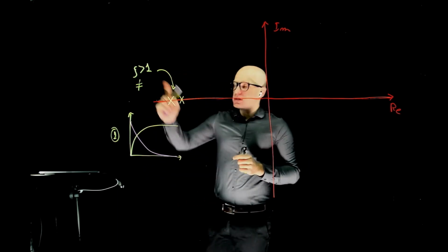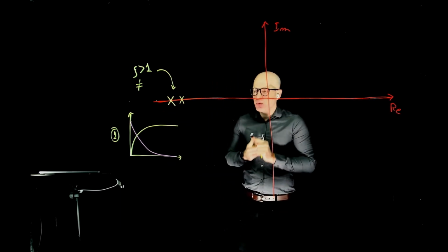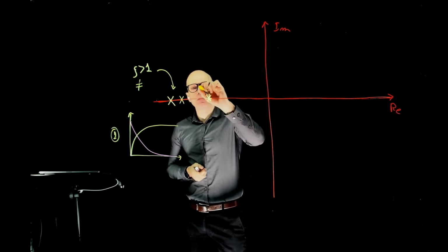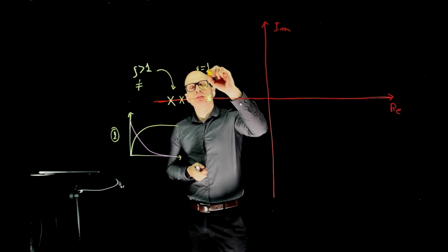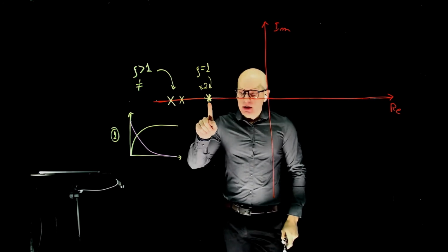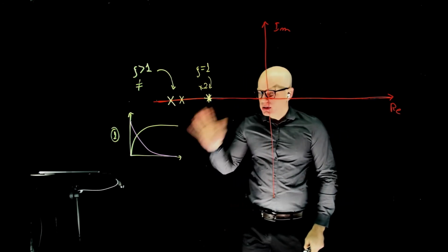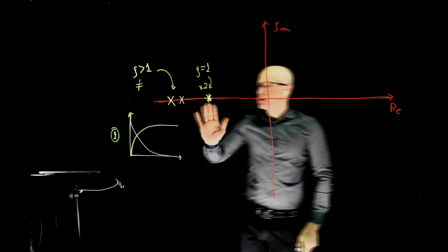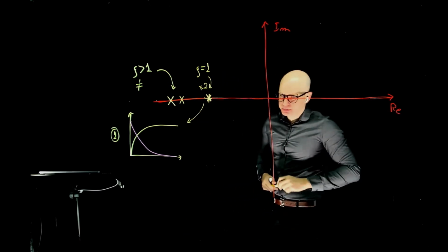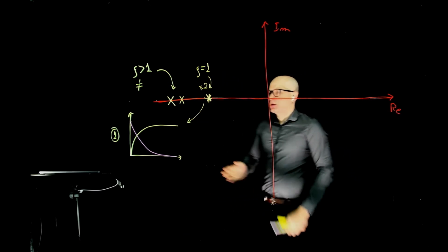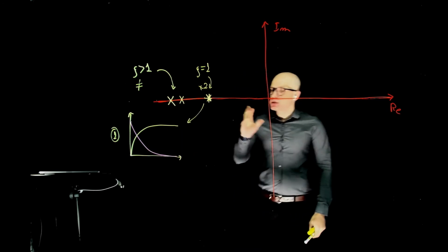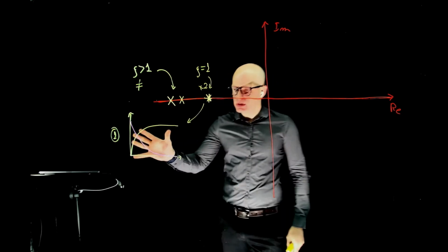As we start to decrease zeta and you reach a point where zeta is exactly 1, then we now have 2 poles that are exactly the same. They're exactly the same, but they are now still real numbers and they still lie on the left side of the S-plane. So the real parts are negative. Because of that, we have the same time response, an exponential that decays to 0. So here is the step and the impulse response for those systems. There is no way to distinguish them visually.